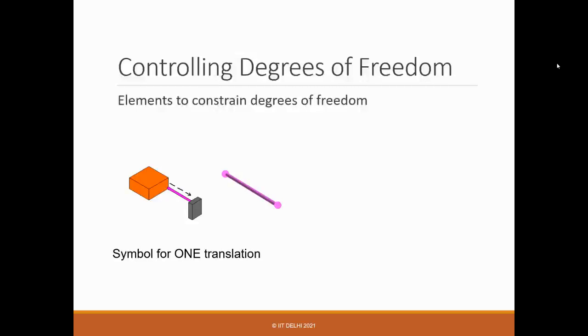So a basic hinge is also one DOF now, right? The column press is also one DOF, and it's the translation. If you talk about a glass door, it's hinged, right? So you have one axis and it should rotate around it, right? So one rotational degree of freedom is desired. So how do we put in five constraints, right? You can start with the constraint lines, and you can also try to explain how the other five DOFs should be constrained, and how you can realize it in practice, right? So that's the one part.